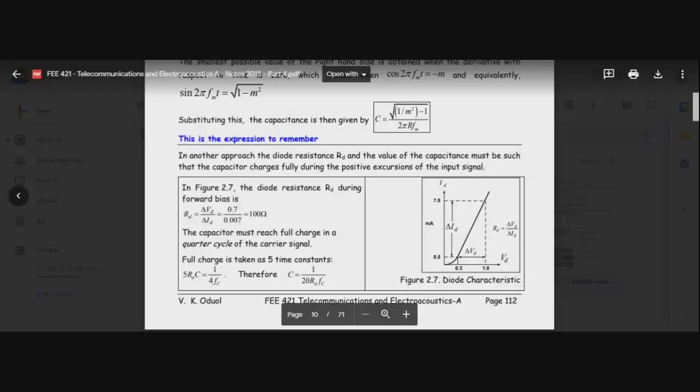You can model the diode output by a straight line starting from, let's say, 0.3, although some books may say 0.7. I don't know why in the diagram I've got 0.3, while there I'm using the diode voltage of 0.7. Oh yeah, it's fine. From 0.3, the kickoff point, up to 1 volt, the drop is 0.7.